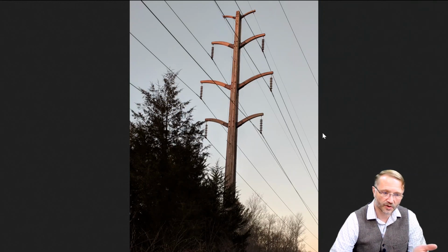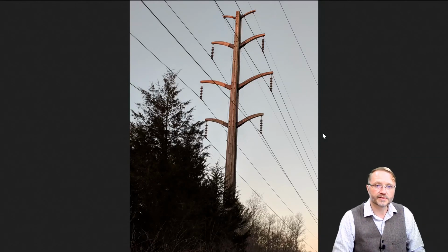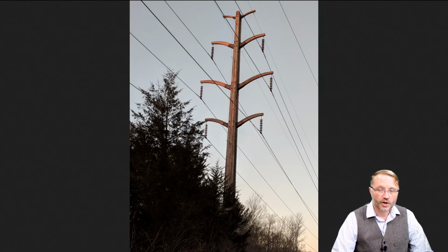You boost up the voltage, which means you lower the current, which reduces the amount of I squared R loss in the power line. You could say that transformers are the one piece of enabling technology that makes our power grid operate. If we didn't have transformers, these wires would be huge. They would be so thick that we couldn't afford to run them. But with the transformers, the wires can be made small because the currents can be made low, with the voltages being high.